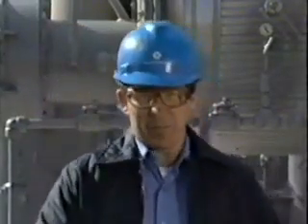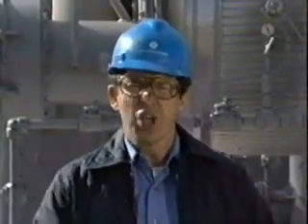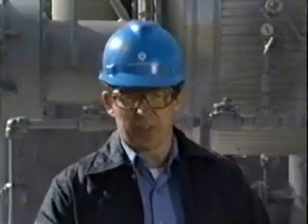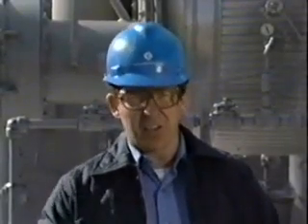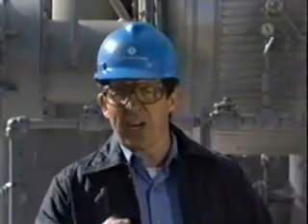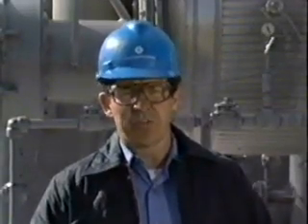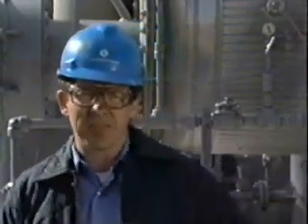During this program on glycol dehydration unit operation, you've had the opportunity to review principles of glycol dehydration, to examine the system components, and to see how to properly operate a unit. Now, if you require additional information, there is an appendix at the end of the third section in your student manual, which includes a troubleshooting guide, a safe lighting procedure for a gas-fired glycol dehydration unit, recommended startup and shutdown procedures, and a chart showing water vapor content of saturated natural gas.